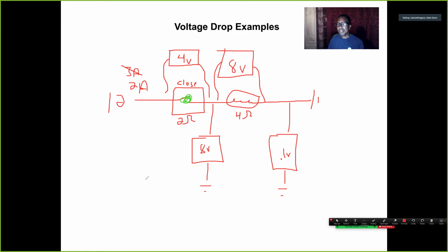And the reason I'm drawing this is because, think about this. Imagine that this point was a relay going to a fuel pump. Instead of being system voltage, I have 8 volts. Imagine this contact was a relay going to injectors. Instead of being system voltage, I have 8 volts. Obviously, it's not going to work, and fuel delivery is going to be affected in both cases.